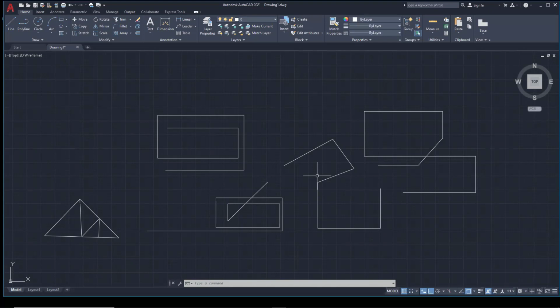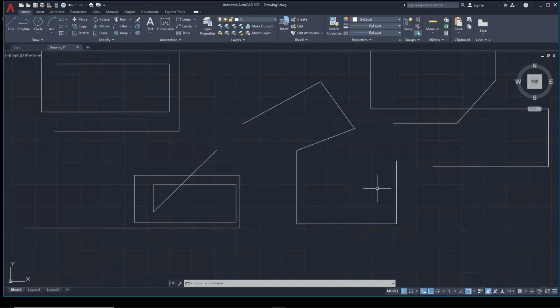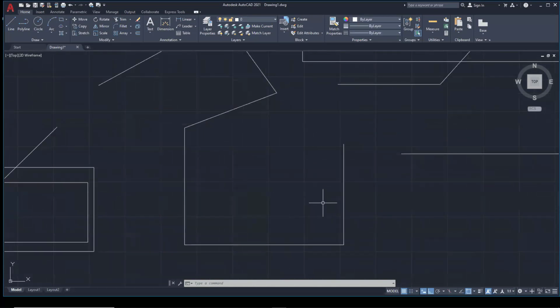No, you can adjust the line. There's a lot of ways to do it, and we'll talk about that more. One of the ways you can do it is using grips. If I click on it, I can click on this grip, and you'll notice that AutoCAD is telling me that that line is 7¼ inches long. But as I move the grip up and down, AutoCAD is changing the length of that line. So if I want to reduce that line by 1 inch, I'll just type 1.